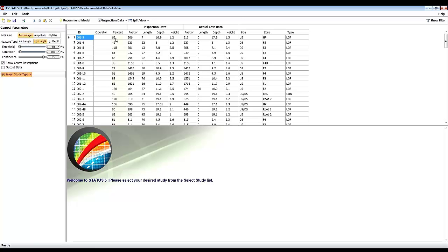Instead, they compare these amplitude levels with the threshold value that you select, and based on that they categorize the defects or amplitudes into 2 categories, hit or miss. The hit ones are the amplitudes higher than the assigned threshold, which the software uses as 1, and the miss would be all the amplitudes lower than that threshold, which the software accounts as 0.